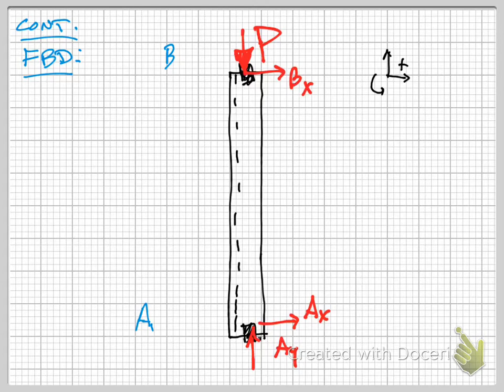All right, because it was loaded axially, we know that BX and BY, AX and BX will be 0. And so we're left with a pretty simple column with a length of, what did we say, 15 feet? Which I believe is 180 inches.